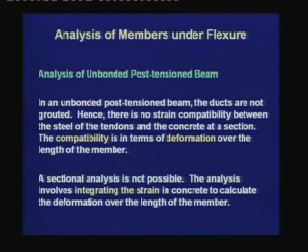Till now, whatever we have studied is for a bonded tendon, and we have assumed a perfect bond between the steel and the concrete, from which we wrote the strain compatibility equations. A perfect bond means that there is a relationship between the strain in the steel with the strain in the concrete at the level of the steel. Now, if the tendons are not grouted, then we cannot apply this strain compatibility equation, and we cannot use a sectional analysis.